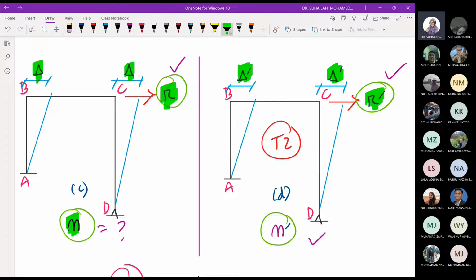So Sidesway, referring to the column, the beam always follows where the column moves. Okay, and due to delta prime, we will analyze the end moment. This is table number 2, and the end moment for table number 2 is labeled as M prime.